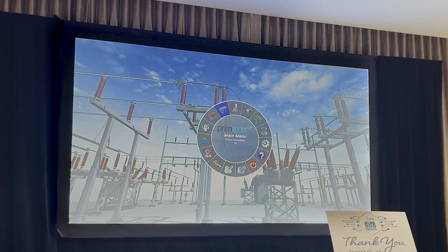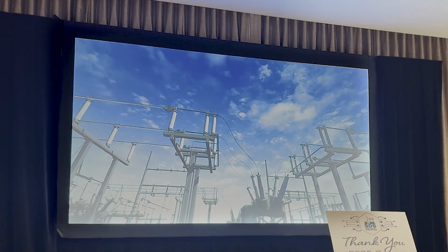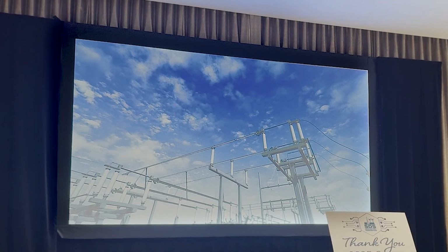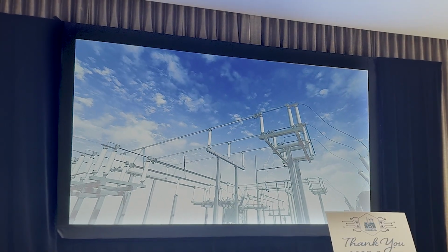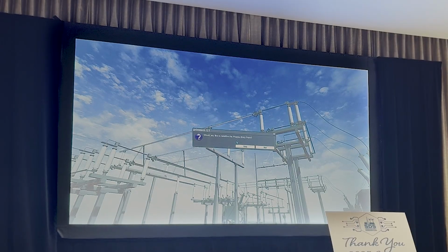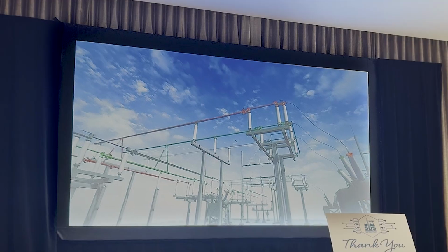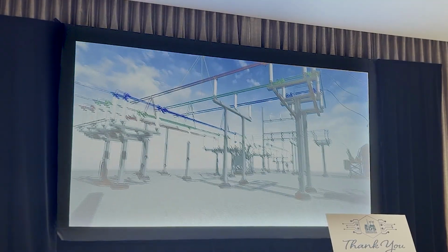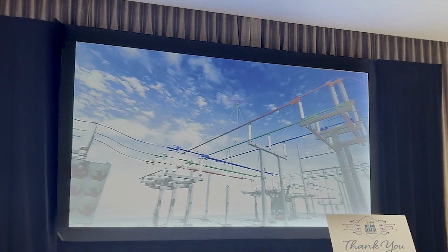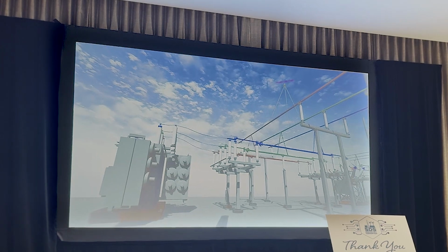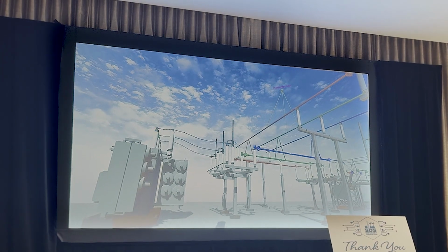Another thing you can do is trace the phasing. Here it's asking me for an entry point for my phases, so I'm going to press Control R to redefine them. I'm just going to say this is the entry point here, just so you can trace it, right? And you'll see it trace across the phases here. You could even open and close these switches.